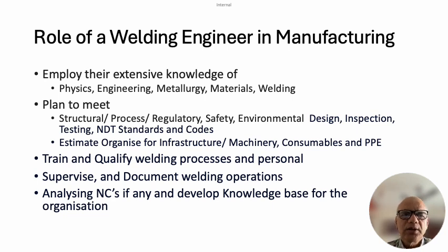Then the role of a welding engineer changes. Now everything is set, the job is already cut, rolled, machined, drilled, and setup has been done. Now he has to execute the welding. So his role is going to be like a supervisor, supervising the operations, that setups are coming in good condition, the cleanliness is maintained pre and post, and during welding controls are exercised, proper dress ups, and then offer it to NDT to ensure that the joints are defect free.